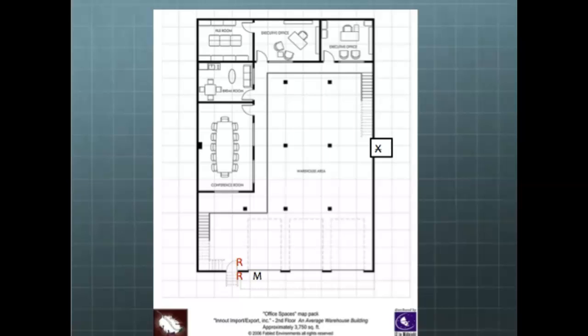Next to the doors where I put the readers, there are 3 dotted blocks. Those are loading docks. And in front of those, the skin of the building has 3 big openings. Those are overhead doors, so trucks can back up and load and unload from the warehouse area. If I use the east door as my main entrance, truck drivers will need to get out of their trucks, walk all the way around, walk through my warehouse. Now, these are people who are not my employees, so I have to get them in somehow. So someone would need to go all the way over there to meet them to let them in so that they could come in and do their paperwork.